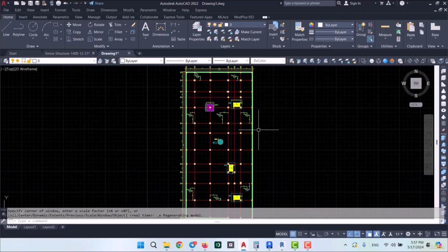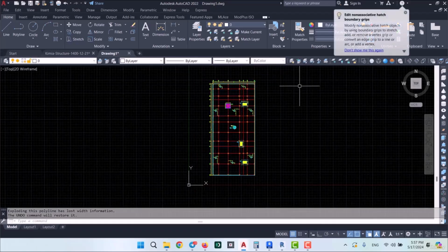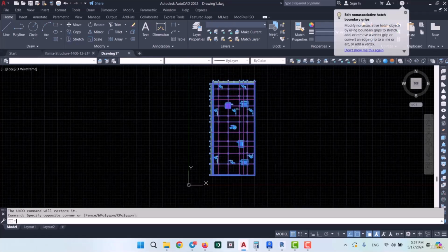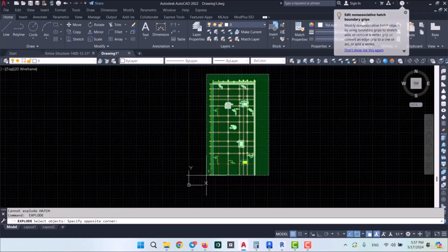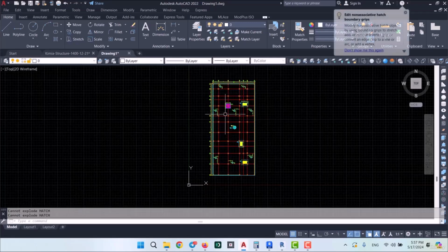Now you probably already know how we can bring a CAD file into Revit, but I'm still going to do it here anyway, so that you could also use it as a review. So first we're going to explode this plan multiple times in order to disintegrate all of the blocks here. Otherwise they might cause some trouble later on. So I'm just going to explode it to make sure that it won't have any problems in Revit.